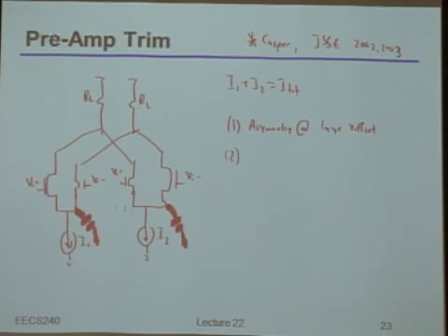So the other thing that potentially is bad in this is that if you really need a large offset cancellation range, it may force you to use a higher V star than you otherwise wanted to use. Which means that again, even though I'm actually using the current always, the relative current efficiency or power efficiency I'm getting is now being limited by this offset range rather than by what I fundamentally needed to drive the signals at a certain frequency. Is this clear to everybody?